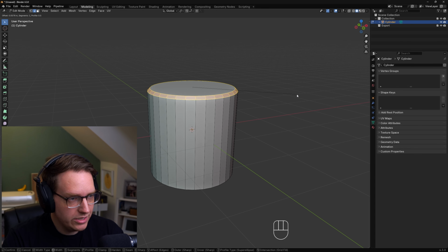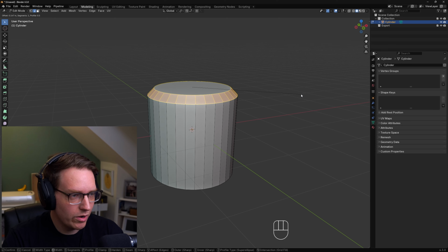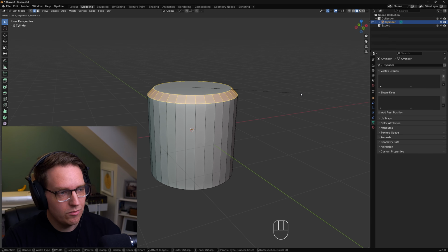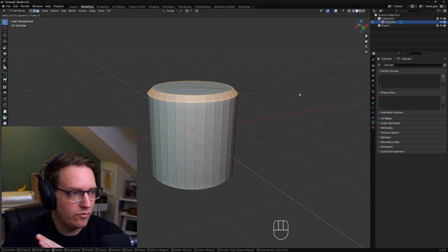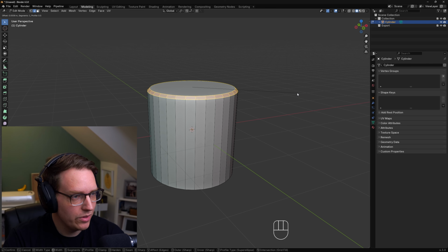So this is creating an additional face between where we had that edge. And what it's doing is putting what is referred to as a bevel, a 45 degree face between the 2 surfaces that we originally selected with that edge. And this is a great way, you'll see it a lot in video games, sci-fi stuff, to put a little bit of a chamfer, which is also a word, similar but different, onto our thing.